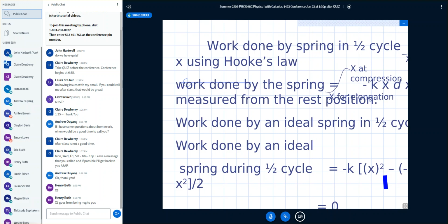There is a technique like this used in industry in order to measure what a spring constant is. When they're making springs, usually they try to have about 10% that they pull off and test to make sure that the specifications of the springs that they're making are met, whether springs for trains or cars, for quality control. This is a technique that they use. I don't know if any of you are interested in that. Anybody interested in that? Do I have a yes?